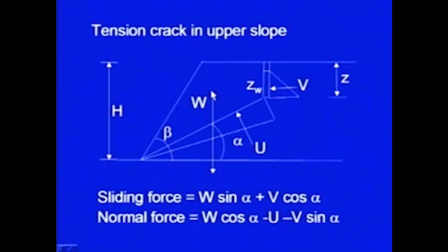We will be finding out the forces which are trying to create instability, meaning all the forces which are in the tangential direction, tangential to the fracture plane, and the forces which are trying to enhance the shear strength by increasing normal stress. So, we will be finding out the algebraic sum of all the forces acting normal to the joint plane or the fracture plane.